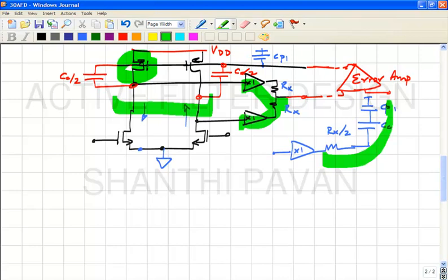And as I said, something that surprises a lot of inexperienced people is, when you design the transconductor, everything looks very nice, phase margin is good, and the step response looks very clean and beautiful, and then you put two of them together and whoa, what happened? The whole thing is oscillating, okay. The reason is that the common mode gain of each one of these transconductors is much too high. All right. Is this clear? Okay.